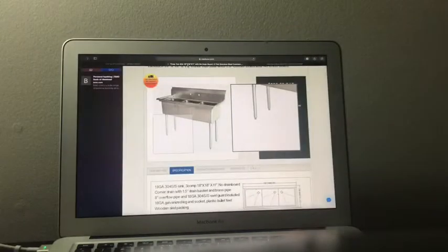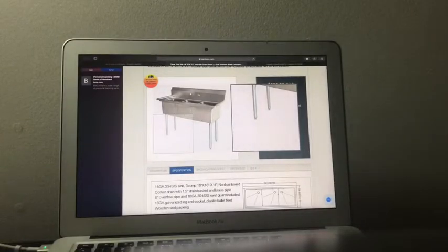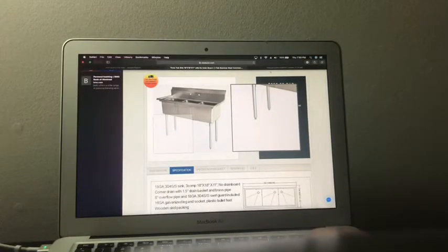Let's take a look at that for a sec. This is the dishwasher example where you run into it most. And so you have a 3-compartment sink here. Then you've got to put 1.5-inch traps. This pipe poking out of the floor or the wall has to be 2 inch. It has to be one pipe size larger. Okay.